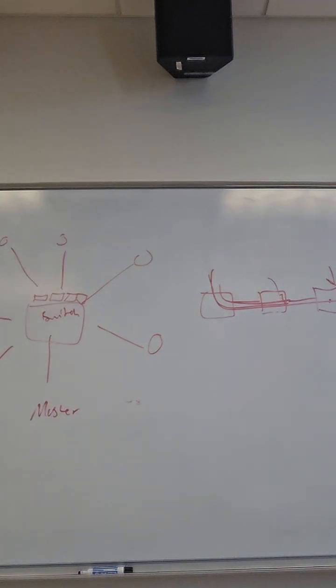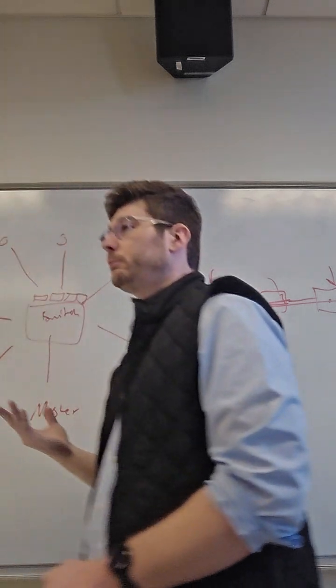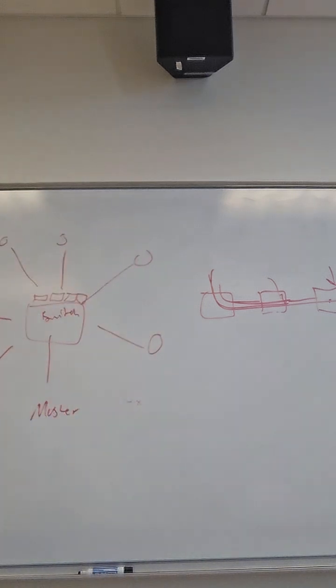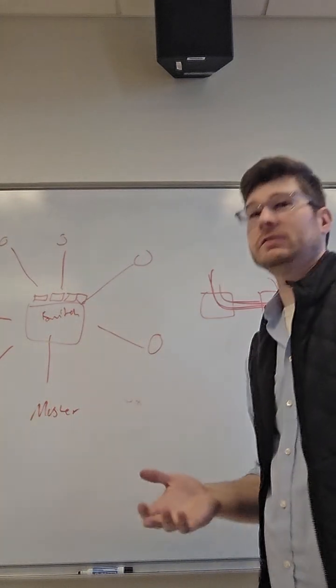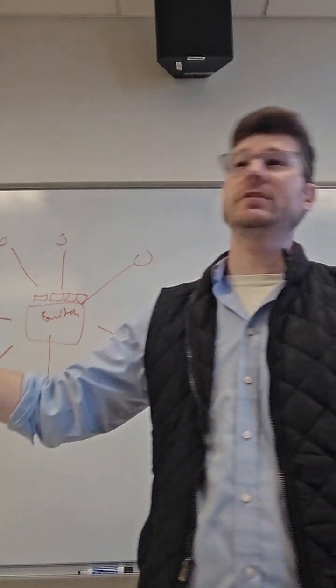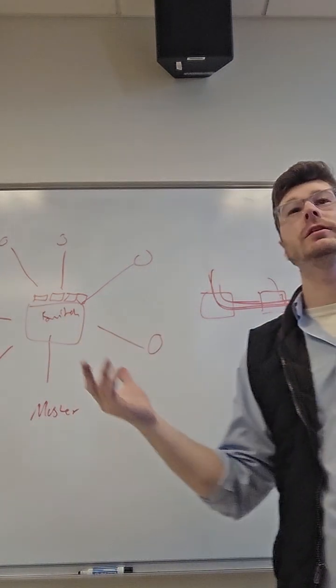Okay, Modbus TCP is definitely faster than Modbus RTU. With this serial type, when we're talking about baud rates, that's like dial-up rate. We're talking about kilohertz, or thousands of times per second. But with Ethernet, we're starting to get to gigahertz, right? Like millions or billions of times per second that we can change the signal. This is often higher-order PLC to PLC communication. Remote communication, like if you have a control room in a different state, you would have that networked through Ethernet to other devices, for example.